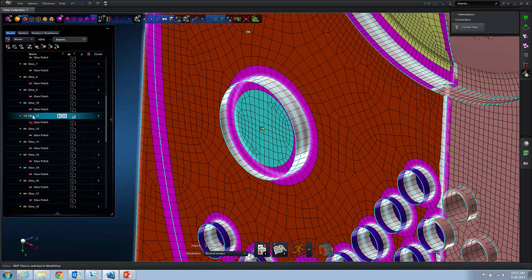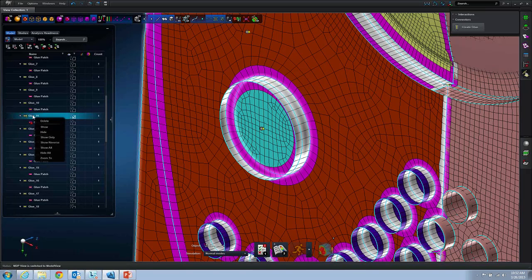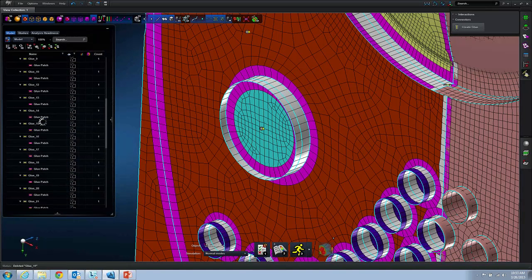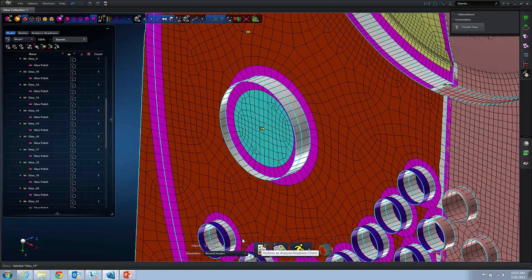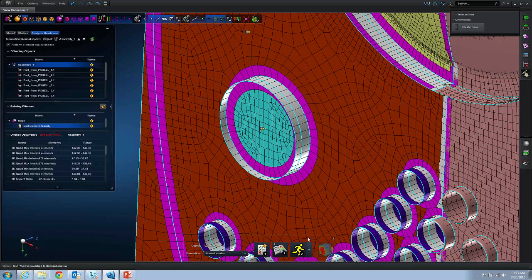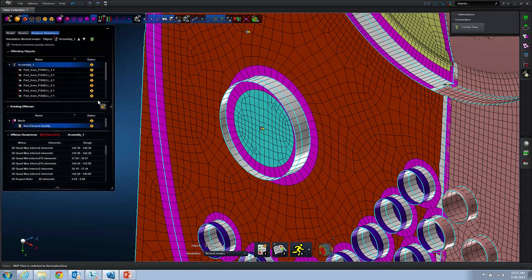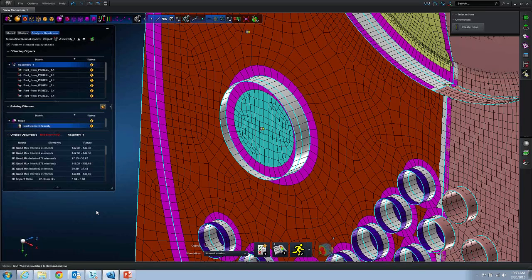So what is the option we have? Once I identified the issue behind that one, I'm going to delete that one. And now if you see here, I can click on this solver validation to make sure the model should be ready for further steps. And as you can see now, everything is yellow, which means there is only information, there are no issues with the model. And creating the assembly representation. Now this is just about ready to run the simulation.